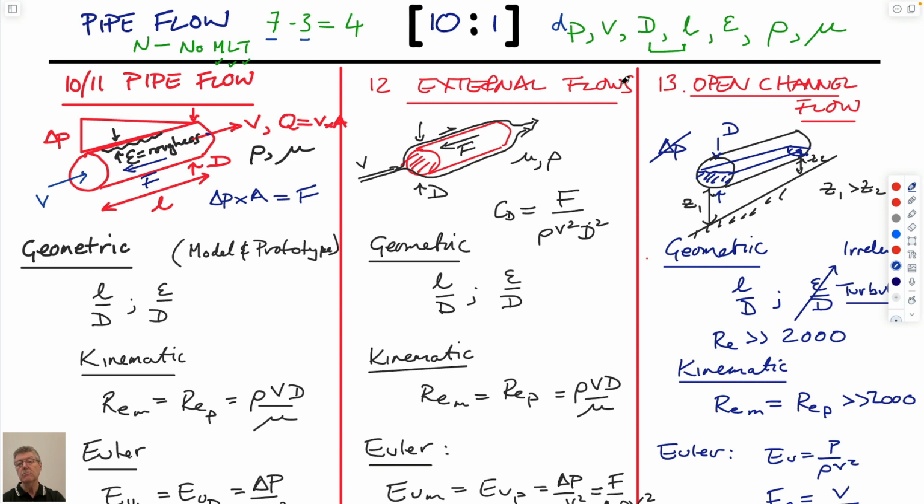And so this has mass per unit volume, per unit length cubed. So mass and length are in this. And time, this is Pascal seconds. So time is certainly included in this, and also velocity is equal to length over time. So we have mass, length, and time included. So we know from Buckingham Pi, if you've looked at, I think, 9.3, that the number of variables that describe the system is going to be 7 minus 3, which is 4.